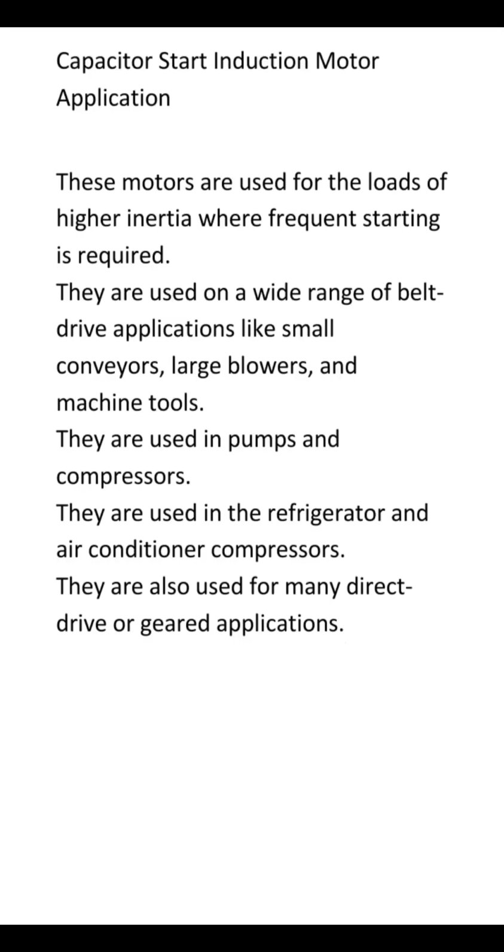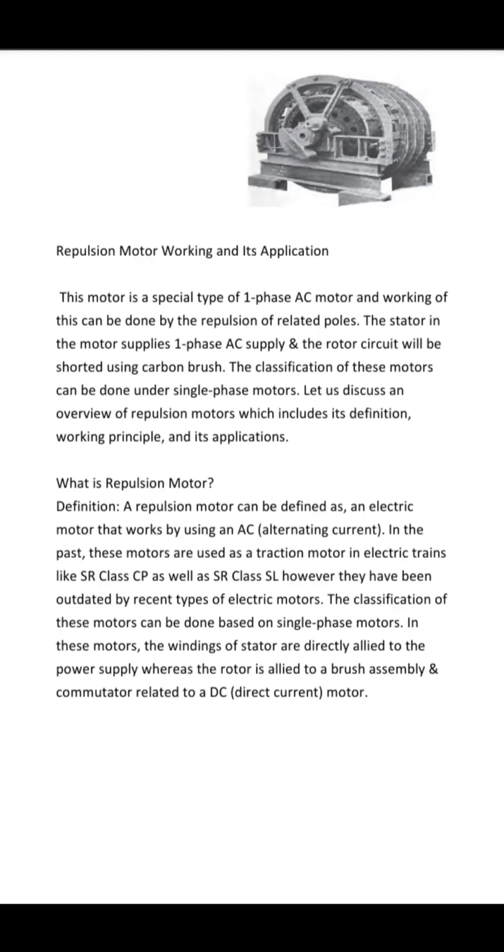Capacitor start induction motor application. These motors are used for loads of higher inertia where frequent starts are required. They are used on a wide range of belt drive applications like small conveyors, large blowers, and machine tools. They are used in pumping and compressors. They are also used in refrigerator and air conditioner compressors, and also used for mini direct drive or geared applications.